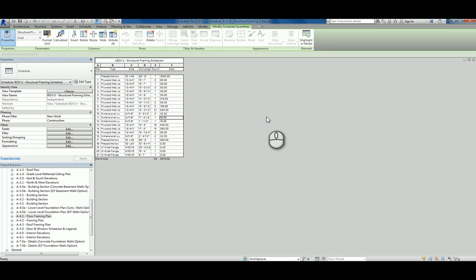I was trying to create some for some of the major assemblies. I think it was Anna, somebody was creating actual schedules for me based on particular wall types, and as people were providing me perimeter and things like that, it was all coming right out of Revit. So as the design changed, I could quickly update. Yeah, and that's, I would say, probably the most beneficial in the immediate for when we're working on projects, being able to get that information out quickly and accurately.